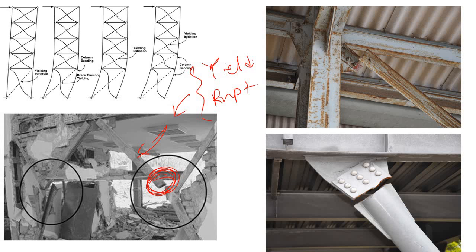And in many cases, you know that the member itself is strong enough. The weakest part of any structure is its connection. Okay, right? So here you can see that the connection is strong enough, but as the member was weak, it has failed first due to yield, then it has simply ruptured.